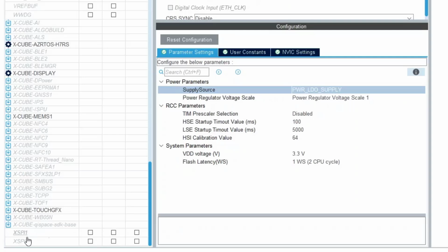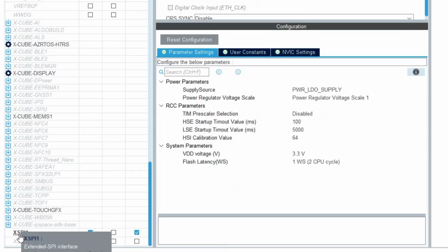The difference between them is mainly the address area when the memory map feature is used. For the XSPI1, it's 0x90000000. For the XSPI2, it's 0x70000000. And I want to use it inside the bootloader because the bootloader needs to enable the external memory, and also inside the external loader. Inside my application, I don't want to use it because I will already run from the external memory, so it will be already configured, and I don't need to do it from the application.